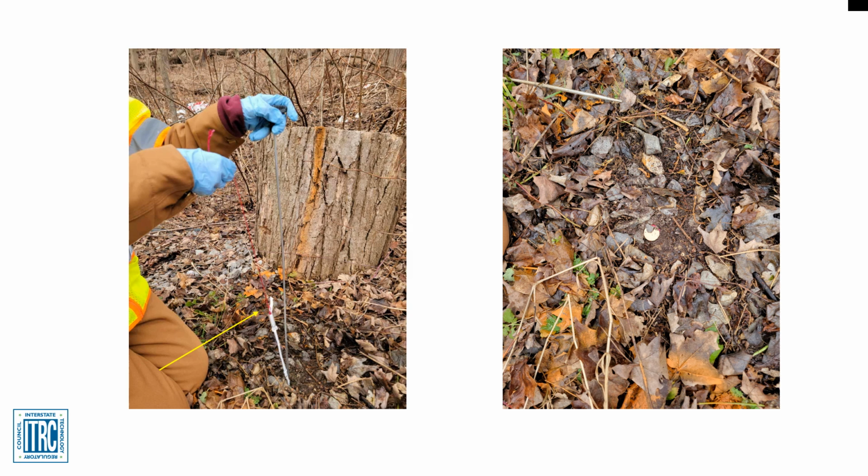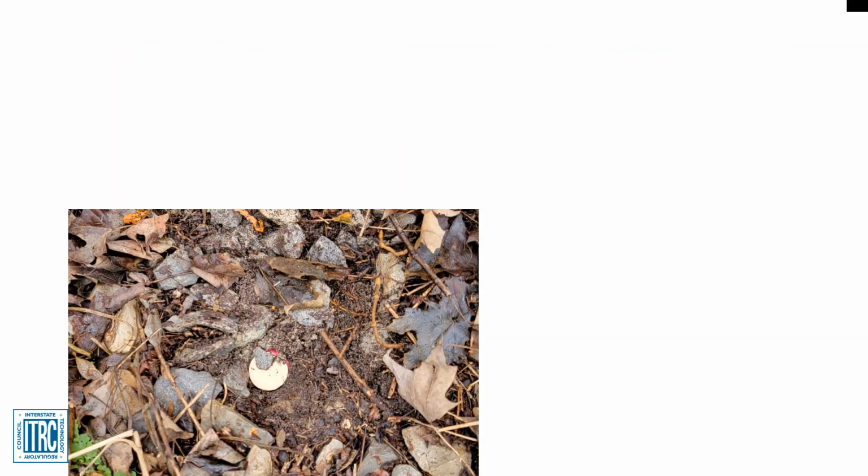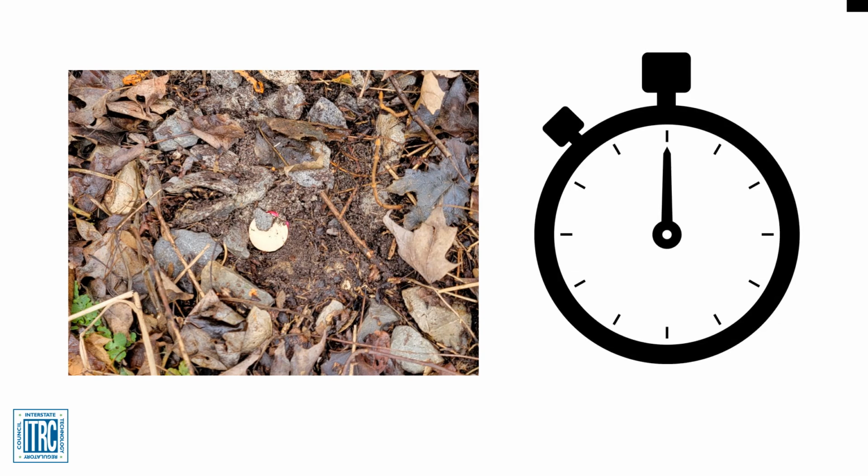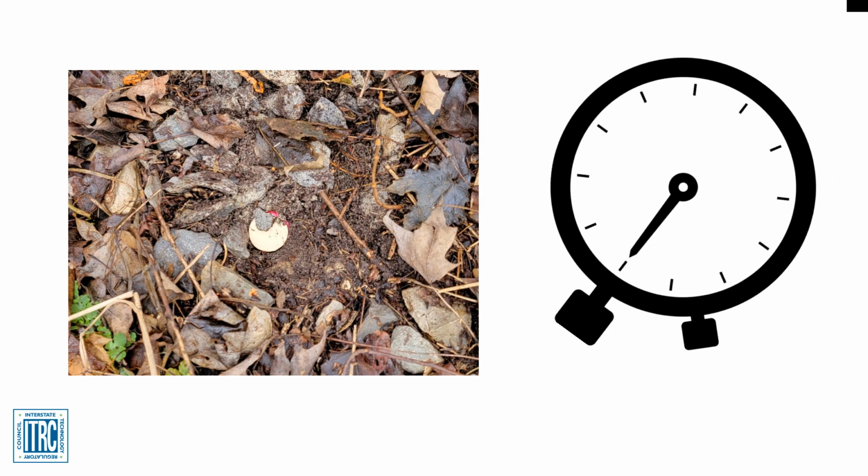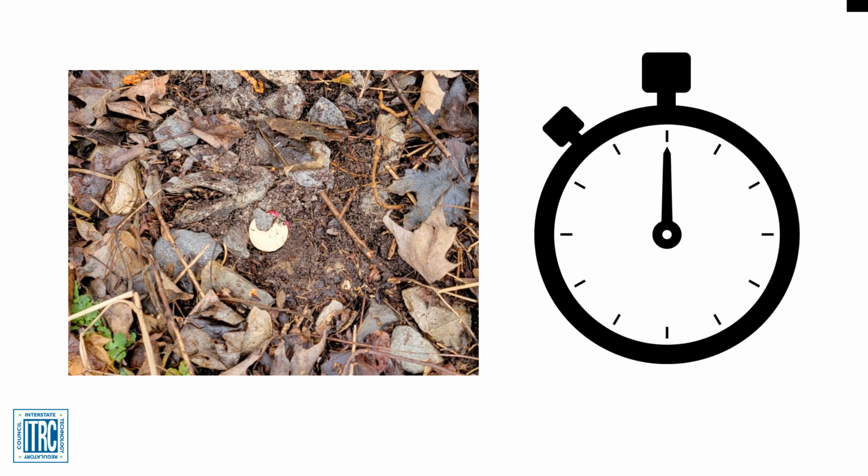Once the sampler is pushed to the target depth, the rod is detached, ideally by twisting, and removed from the borehole. The string, which extends up from the sampler and is looped through the bottom of the cork, should be tied and knotted. The cork is then used to seal the boring, and the field personnel records the installation date and time. Once the sample collection period is reached, typically 7 to 10 days, field personnel should take the following steps to retrieve the sampler.